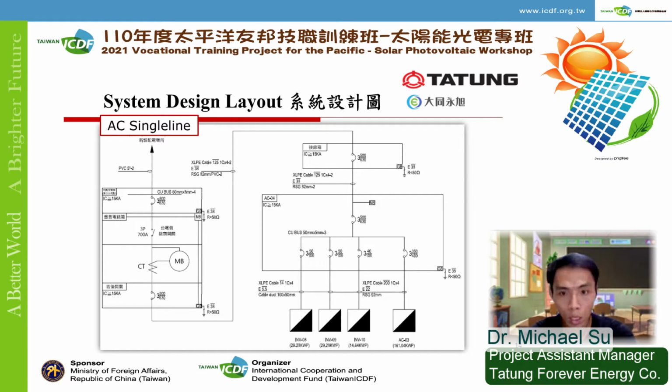Now after drawing the AC single line diagram, I would also put down the number of corresponding inverters, their capacities, and the kind of cables that are being used. Also their diameter and measurements, and also where the switch is. I will put them all down in the chart.